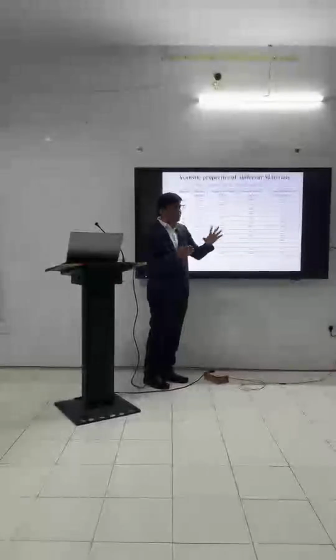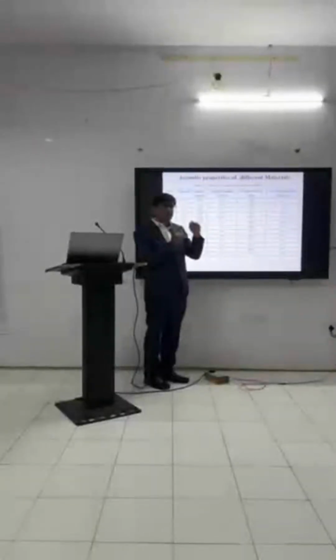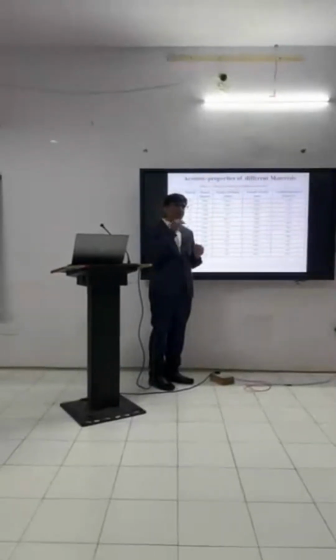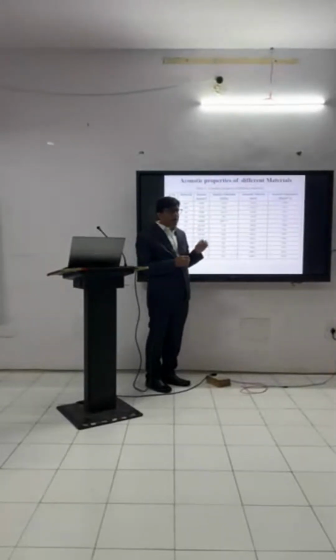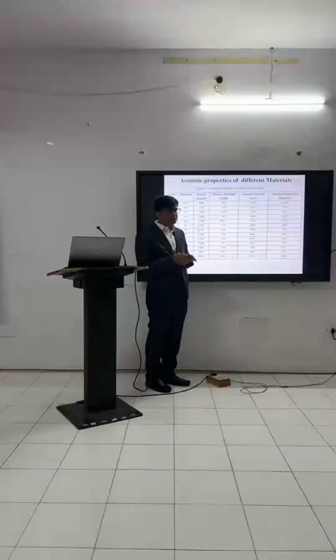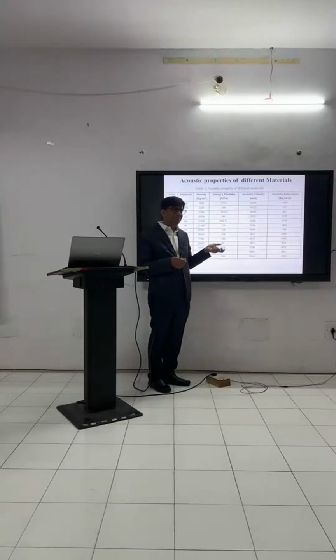Based on that, I can decide about my frequency. If I am looking for very high frequency, then I go for aluminum nitride. And if I am looking for a simple sensor, then I can go for ZnO. But still, you have to optimize.